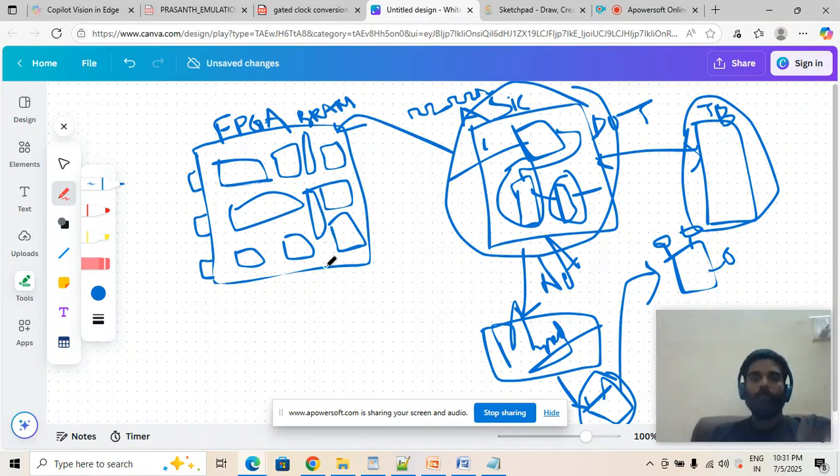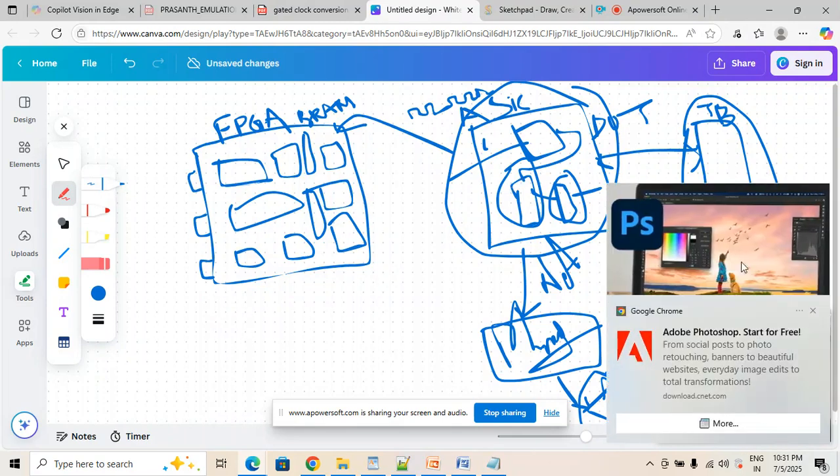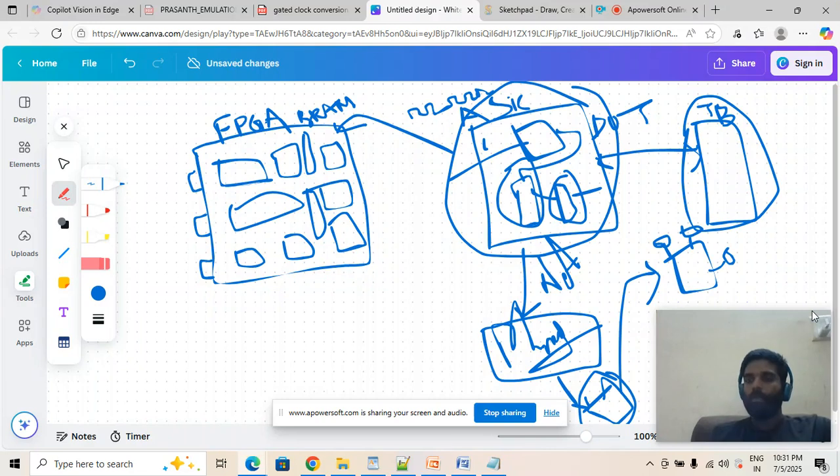So with the given options, we have to make some kind of changes. We can't make a change in the RTL at the same time. So we have to provide some input to the tool, right? That you need to go and consume these dedicated block RAMs. So that we need to mention to the tool. Okay, so that's one thing, memory. And reset-wise, for example.